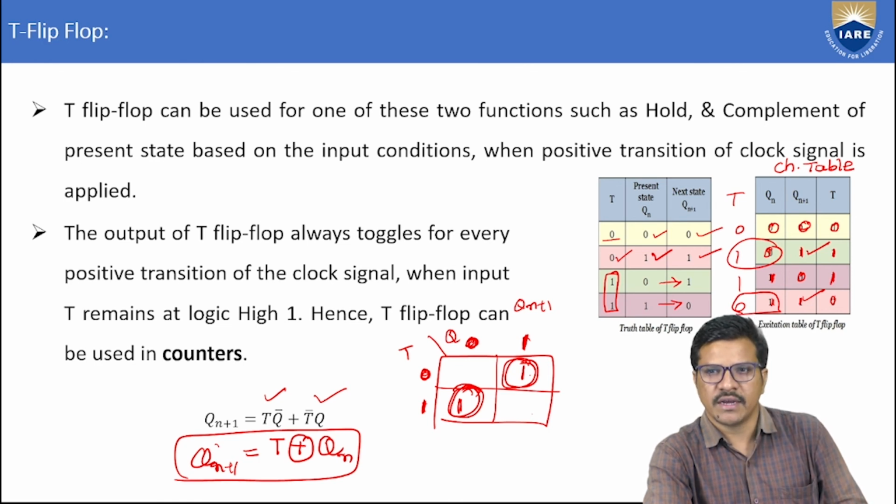The simple SR flip-flop is a basic foundation flip-flop, and then the JK flip-flop. Most probably we prefer the JK flip-flop and T flip-flop in counters, synchronous or asynchronous, and most of the time we use the D flip-flop as a delay or buffer.